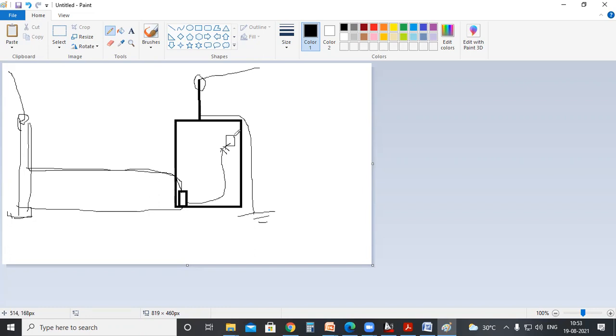So to make sure that we are getting equal protection from the surge current and the lightning, we have to provide a lightning protection system, and at the panel incomer or the DB incomer, we have to provide a surge protective device.